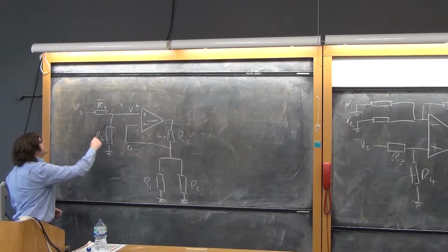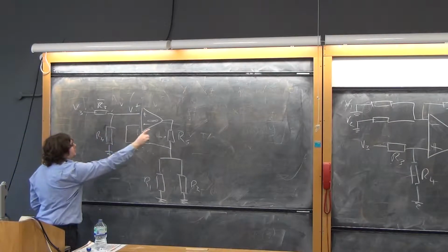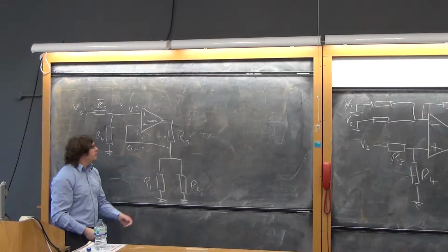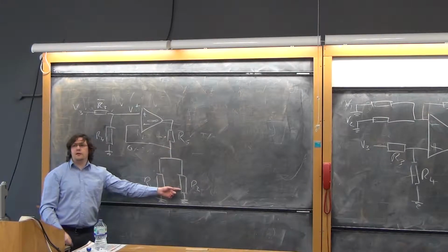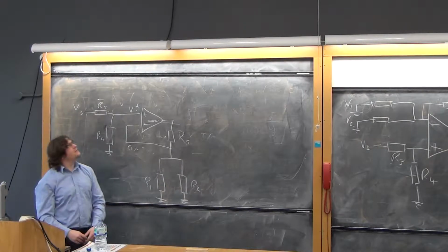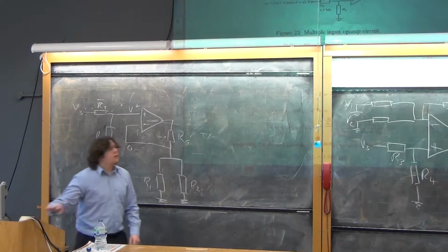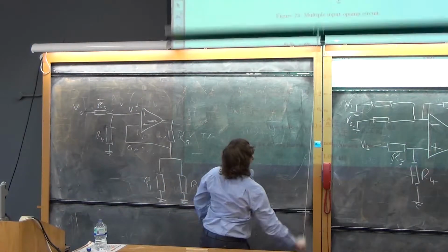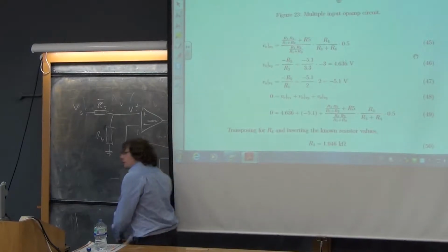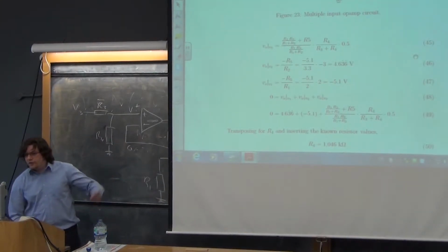So we can treat the potential divider and the op-amp separately. So we can work out what the gain is for the op-amp, and we get 1 plus R5 over these two in parallel. Yeah? You see where that came from? It's 45.